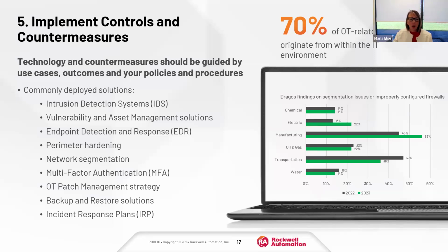you implement. If you think about implementing an IDMZ, so that industrial demilitarized zone, if it hasn't been designed according to your requirements and allows you to communicate the data sets that need to be communicated via the IDMZ up into your enterprise layer, it's either going to leave you vulnerable, or it's going to be a complete block so people can't communicate, and they start to bypass and find ways to go around it.